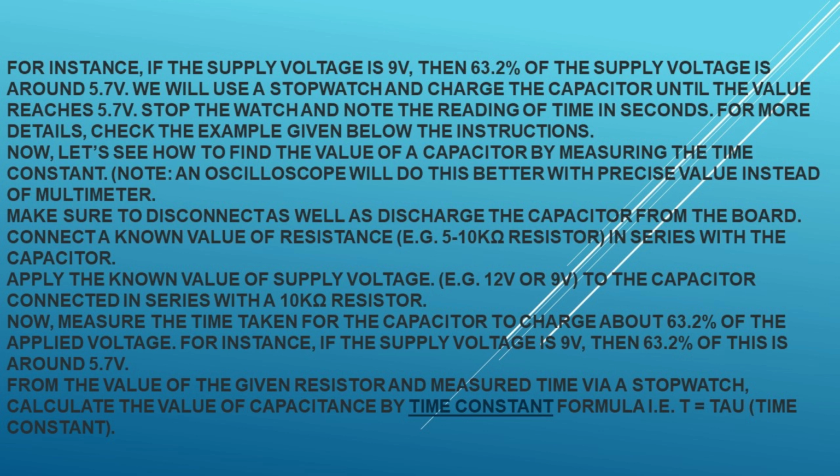Method 4. Testing a capacitor by simple voltmeter. To apply this method on polar and nonpolar capacitors, you must know the nominal voltage of the capacitor. The voltage level is already printed on the nameplate of electrolytic capacitors, while there are specific codes printed on ceramic and SMD capacitors. You may follow this guide which shows how to read and find the value of ceramic and non-polarized capacitors with related codes printed on them.